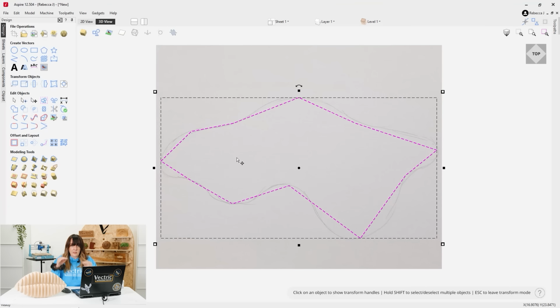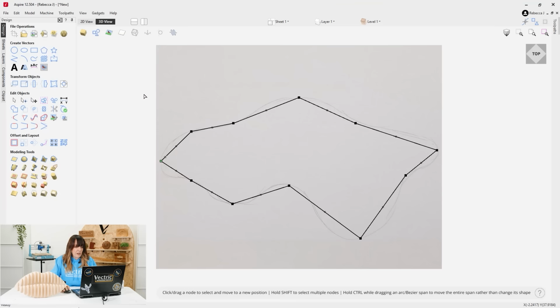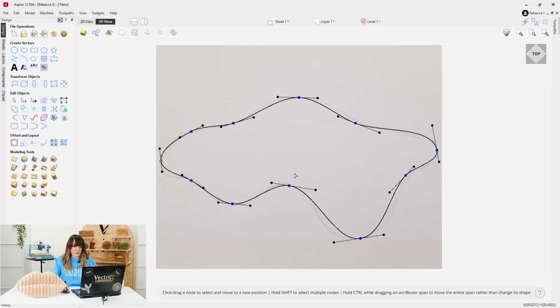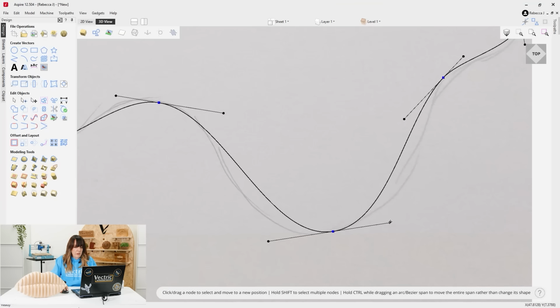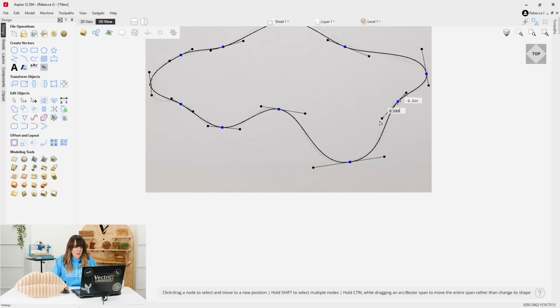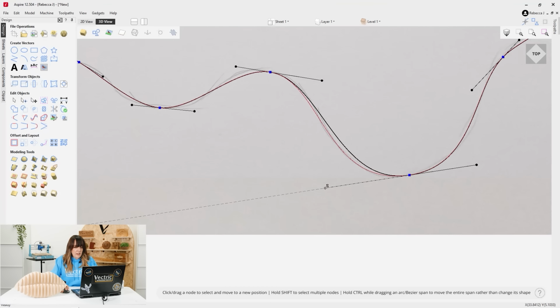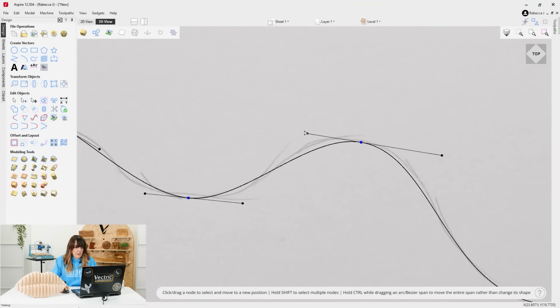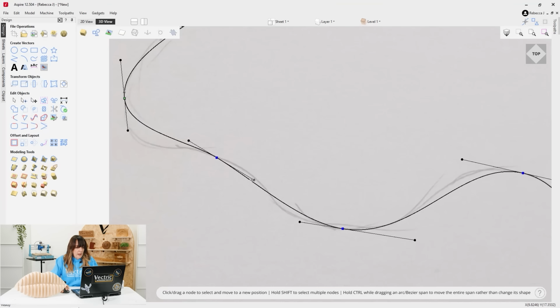And because I've pinpointed all of those curves, I'm able to easily just transform those into smooth points, and generally it should follow the curvature, which you can see it's done pretty well here. So all I need to do now is just go in and just tweak those handles, pull on the handles, move those nodes around until it looks like the actual drawing that I've got from the photo. So we're just going to move that over here, and then we'll pull that over there.